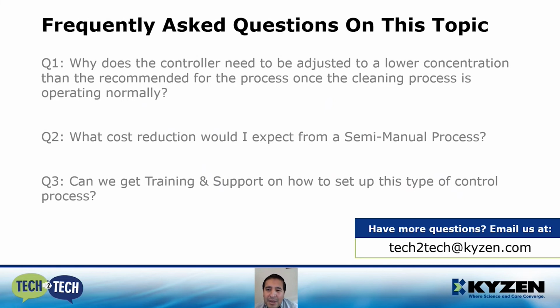So, like I was mentioning before, depending on the different factors involved in your specific cleaning process, chemical and water will be consumed at different rates. For starters, water has a boiling point of 100 degrees Celsius. We might not heat the solution that high. Usually it is set up to 60 degrees Celsius, but it is enough to increase the evaporation rate of the water present in the solution. And we lose more of the water from the process through that means.